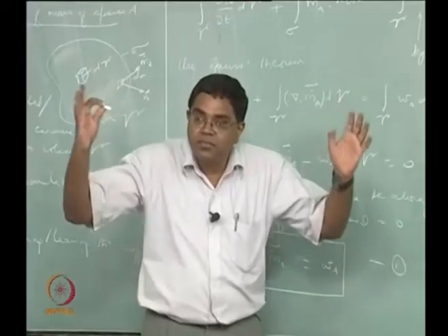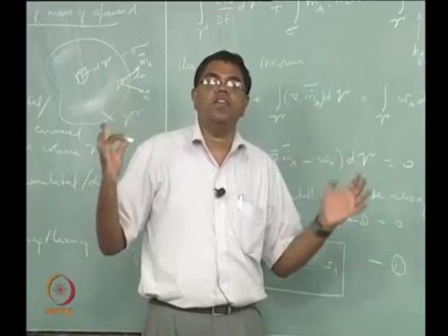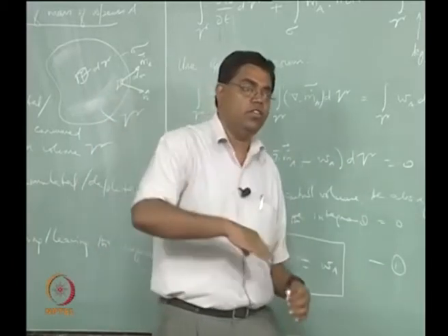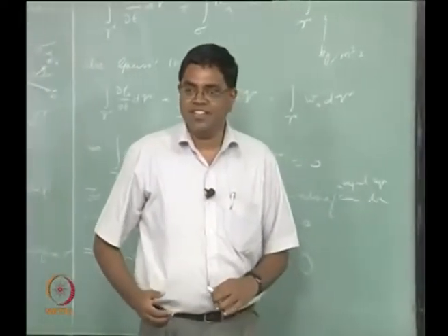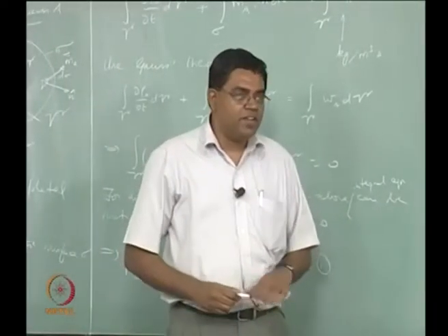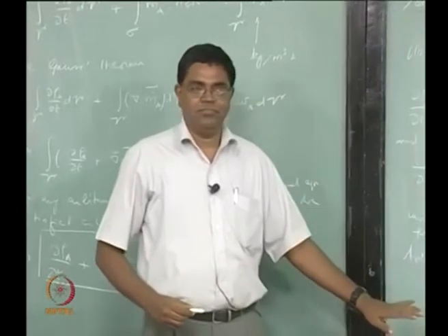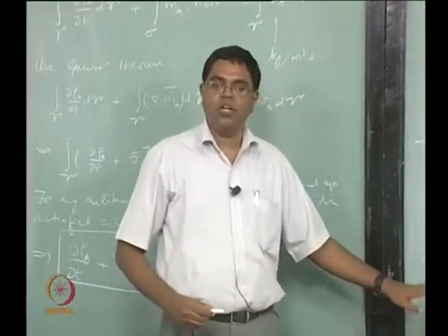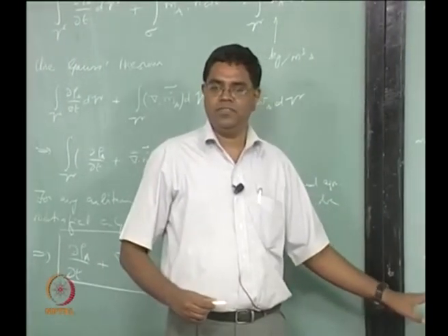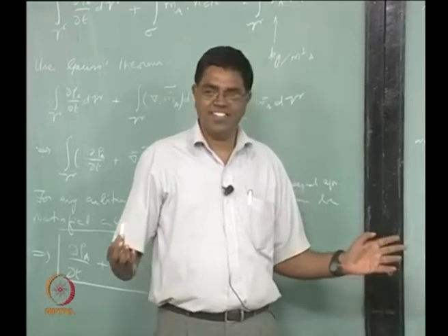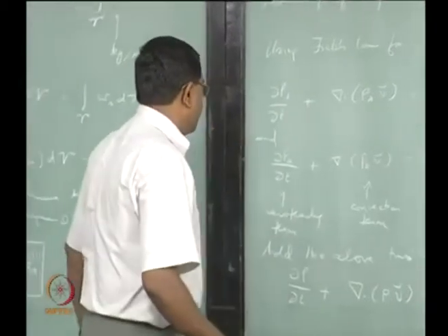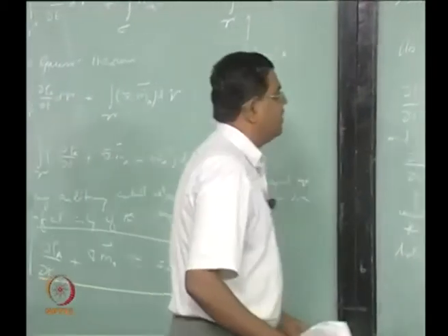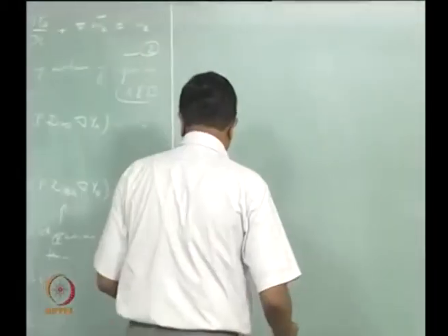As far as the mass conservation of the mixture, you will find that there are effects in the energy of the mixture and so on. But as far as the mass of the mixture is concerned, it didn't matter that you had a multi-component reacting flow. Isn't that kind of interesting? So you get back your mass conservation of a mixture as if it's a non-reacting single component situation.